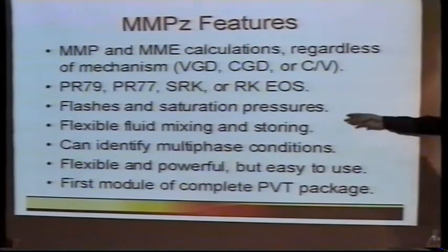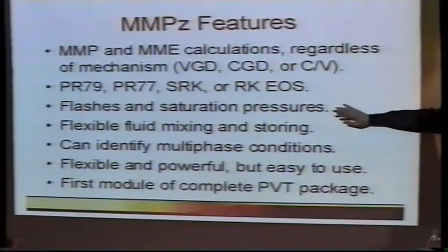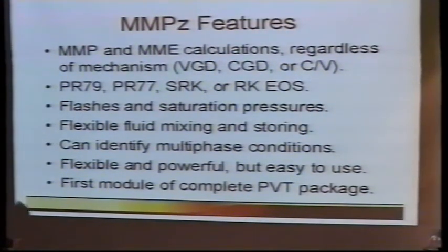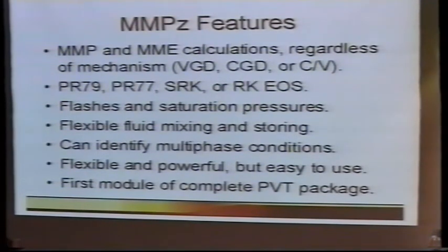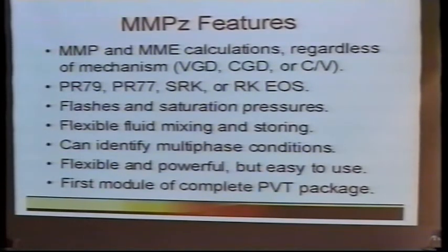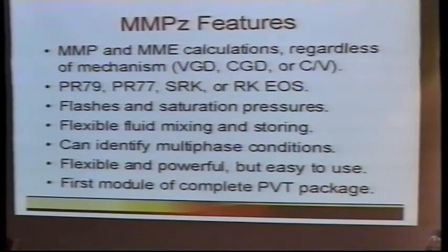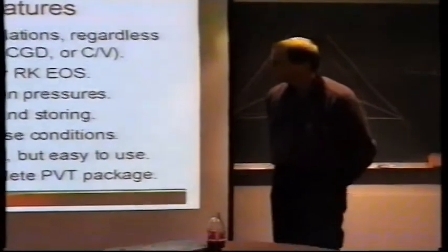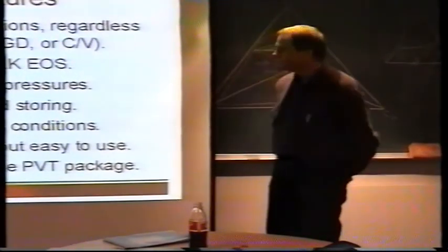I've actually added quite a few more features beyond the flash and saturation pressures already. You can do any of the normal experiments, CVEs, DLEs, constant composition expansions, swelling experiments, multi-contact experiments, vaporizing type multi-contact vaporization experiments. So you can do all of those things now too.